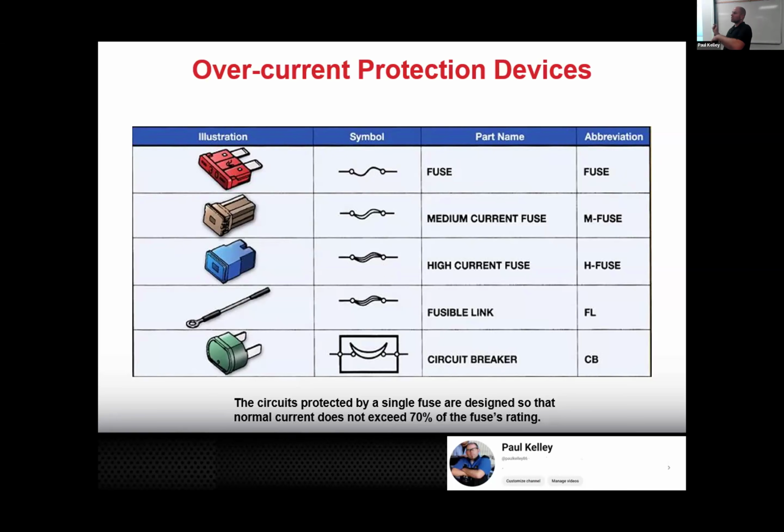That can cause too much current and blow a fuse, which is kind of like, hey, every time it gets icy, I blow the fuse. So they won't use a fuse, they'd use a circuit breaker, and they may make it a PTC, a self-resetting circuit breaker. So you go to run your wipers and mirrors and windows and they don't work. But then you drive the car and it thaws, and it resets the circuit breaker and they start to work again.